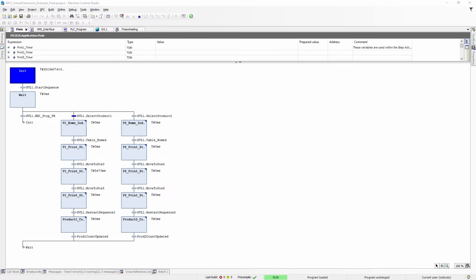In terms of hiding and showing things? In terms of the different pages within the pages. Oh, so you have, can you go back to your home page, for example? Oh, so you've got a settings page also? Yeah, I haven't actually got it yet, but I'm just sort of at the preliminary layout idea. Yeah, what I do, I'm a fan of a page for, when it comes to an HMI, I like to have pages organized by function. You know what I mean? At the end of the day, it needs to be such that the operator won't be confused. The navigation needs to be consistent, so the operator's not confused as to where they're at. How do I get here? How do I get there? So yeah, I think yours looks pretty good there.